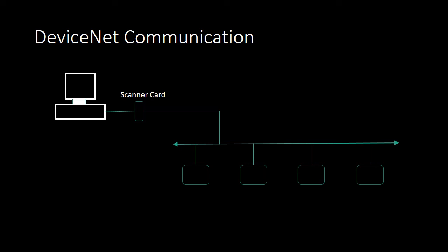A DeviceNet node can be a client, a server, or both, and a client or server can produce or consume messages. A typical node will do both, but the protocol allows several communication possibilities among the devices. The protocol can also detect nodes with duplicate addresses, MAC IDs. Avoiding duplicate addresses is more efficient than trying to locate them later.